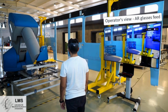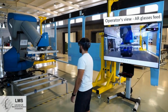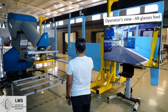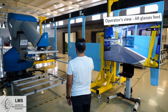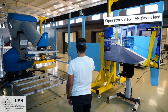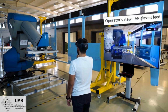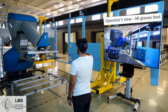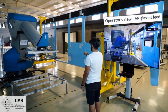The user notices that the frame in the AR glasses view is slightly misaligned, adjusts it, and proceeds to configure the second operation, the move arm. They rotate the end effector 90 degrees to approach the window on the panel side. After turning it 90 degrees, they execute again, and the robot moves to the new position. It's preferable for the robot to make small adjustments during operations rather than moving directly from the initial position to the final one, as this helps avoid collisions. More operations are added for small modifications.